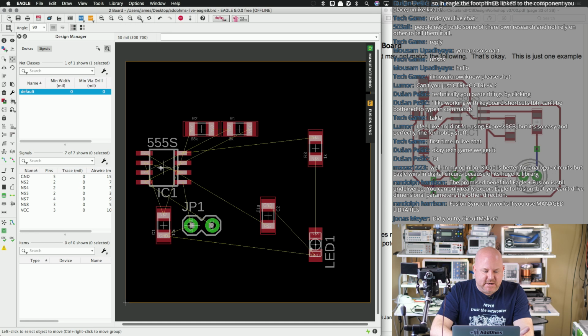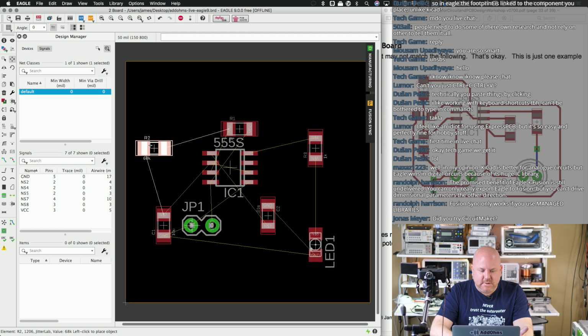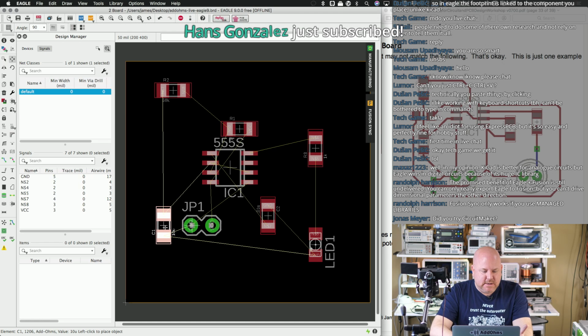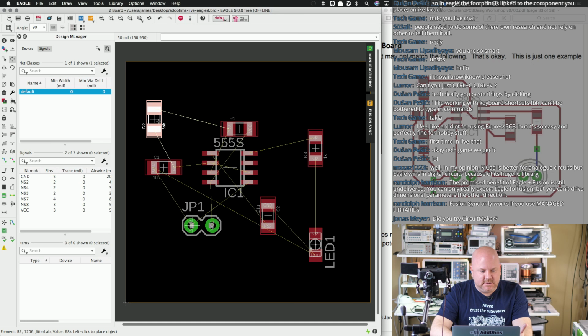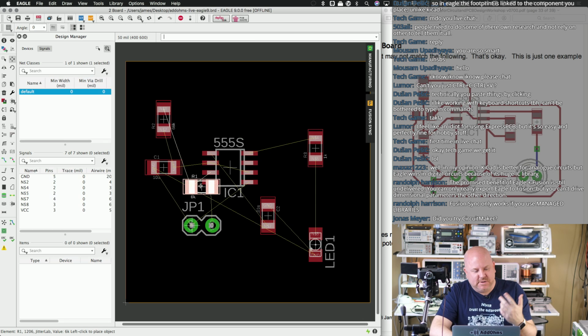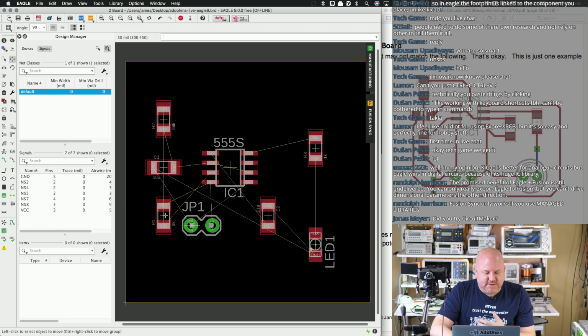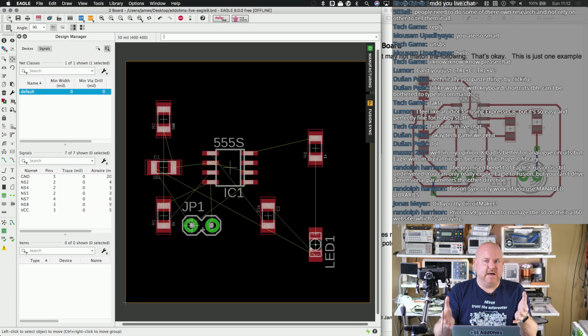Now, like I said, I made a custom schematic symbol, and I made the symbol so that the schematic would resemble the PCB. This was a training class after all. And I do recommend, personally, I like drawing my schematic symbols based on how the parts will be laid out on the circuit board.